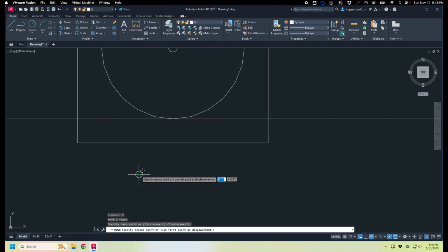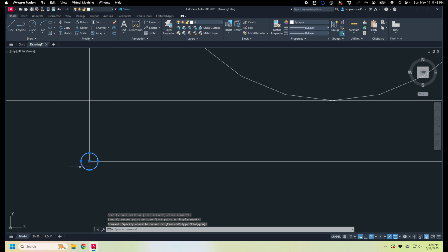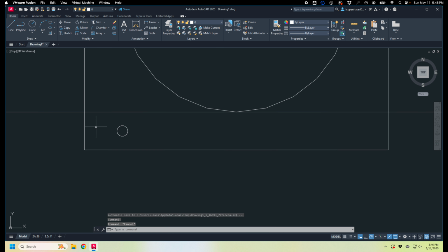And I'm going to place those. You'll notice that I tend to draw things out of place and then move them into place. So I'm going to put that there. I'm going to move it some known distance. Let's say that we want to go 1 inch in, and then I want to go 1/2 inch up. Great. So now that's centered on the place where my 1 inch angle iron is going to be. Great. There's a faster way to do that, and I'm going to show you.